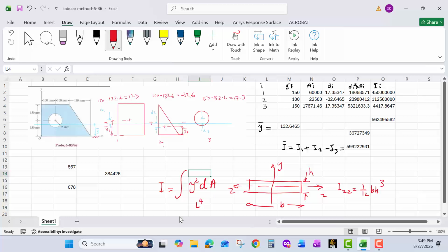Okay, the first problem is when you are bending a composite shape like that, the neutral axis for that should be calculated, and it's not in the middle or some predictable position. So you need to find y bar for that cross-sectional area. That is the first thing.